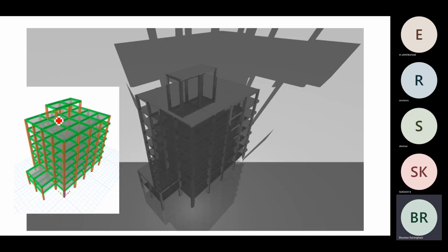So this is one type of example in which there is a vertical projection on top and a horizontal projection at the bottom. So there is a porch and one story above, okay, on one side, and this is the vertical projection. Suppose this building is in zone 3, right? So I don't have to consider vertical earthquake, but still I have to design these vertical projection cantilevers and horizontal projection cantilevers for the vertical earthquake condition, right? So if the building is in zone 3, still I have to consider these two parts, separate them out, and design for vertical earthquake.